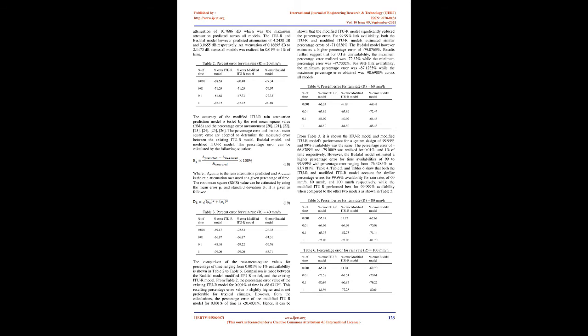From Figure 2c, all three models suggest that for a system design of 5.26 minutes of outage in a year, attenuation values ranging from 10.6293 dB to 33.3658 dB is expected. This comes with an underestimation value of at least 24.1967 dB. For time availabilities of 0.01% to 1%, attenuation ranged from 0.5789 dB to 6.653 dB across all models.